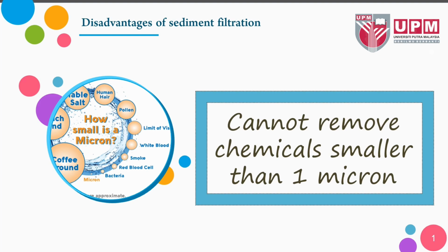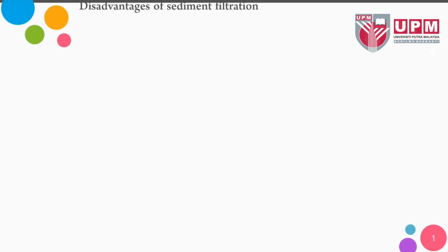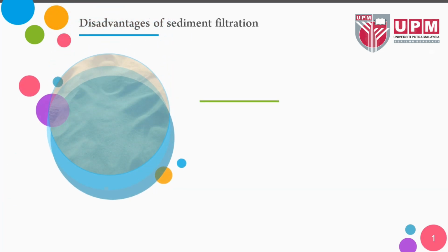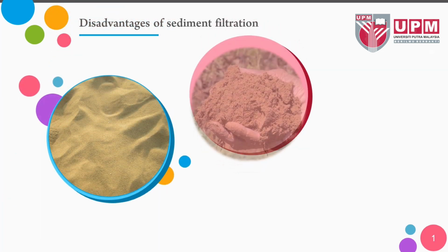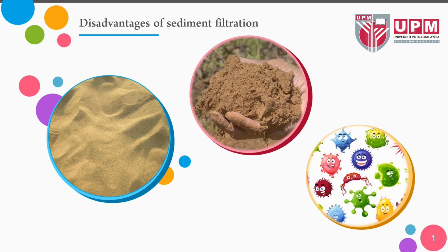Storing water for as little as a few hours will only sediment the large, dense particles such as inorganic sands and silts, large microbes, and other microbes associated with larger, denser particles. However, clay particles and smaller microbes not associated with large or dense particles will not settle under these conditions.